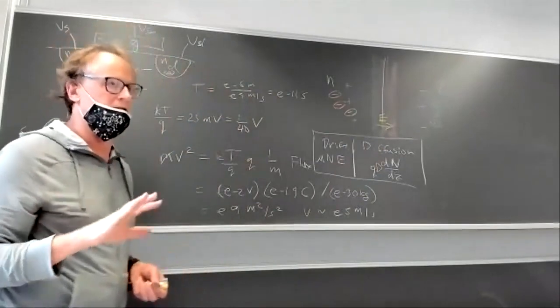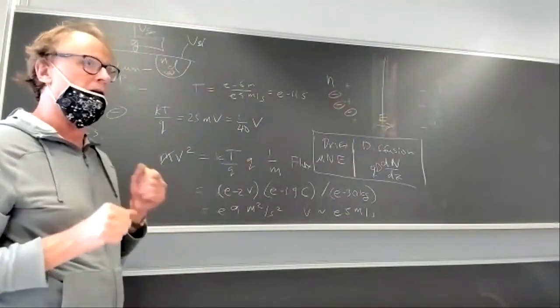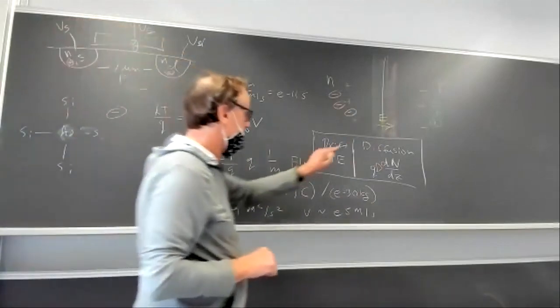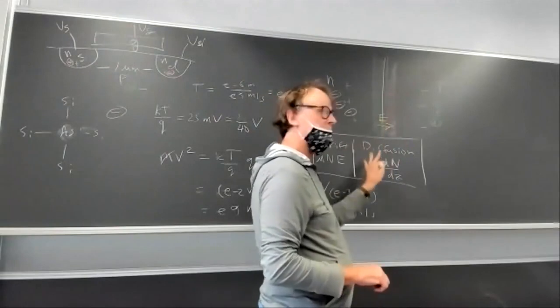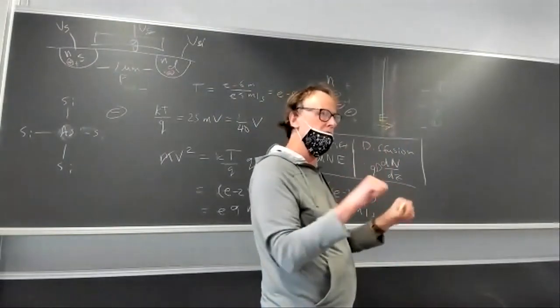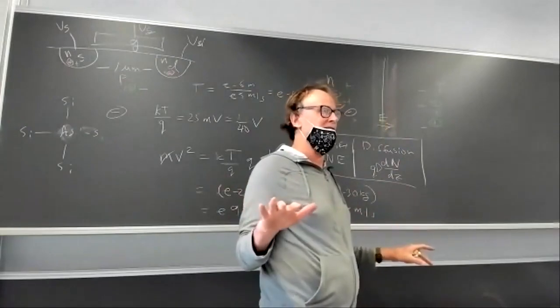Normally, you don't have to know about these to calculate what the transistor does, but you need to be aware that when you have a p-n junction like this, these two currents are in opposite directions and they balance everywhere exactly, so there's no net current.